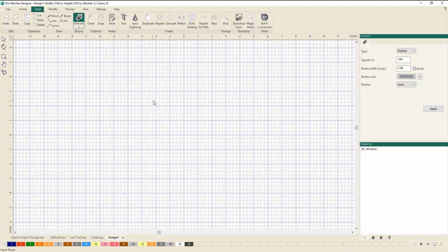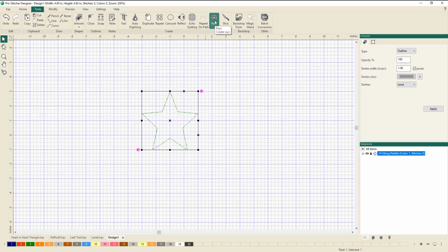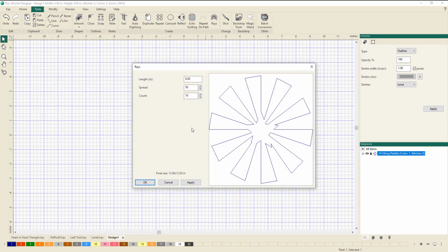So I'm now going to create a star that is 4 grid lines by 4 grid lines. So there's my little star. Okay, so then I'm going to right mouse click or go Q to select the object. Now I'm going to come up to the raise function up the top, so click on raise, and now I can set my parameters.